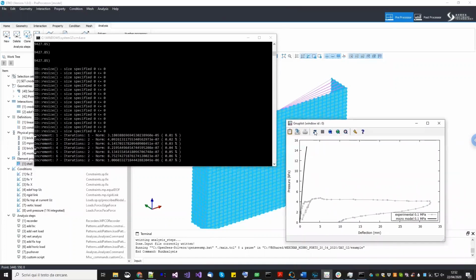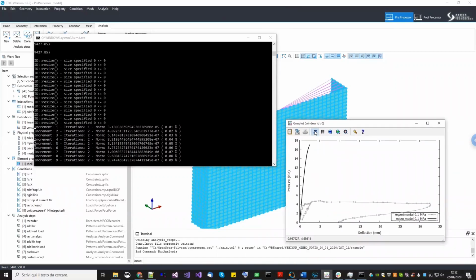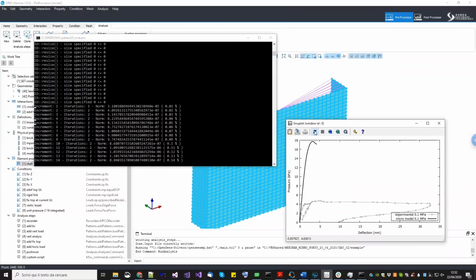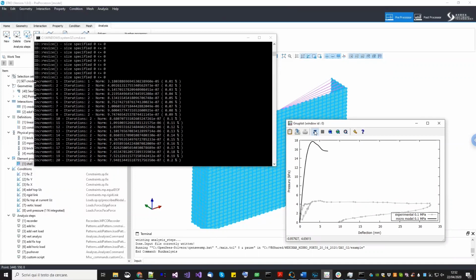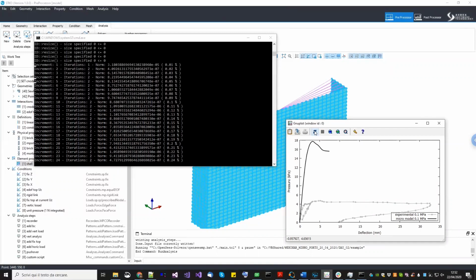So already here, you're a lot above the reference curve, and not by a small factor, by a lot. Then as soon as this finishes, we are going to see why this is happening. So we just changed the shell from thick to thin. So you may expect, well, but the thin shell theory should be better for a more flexible shell.